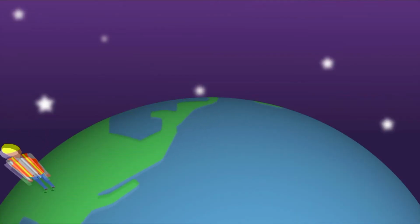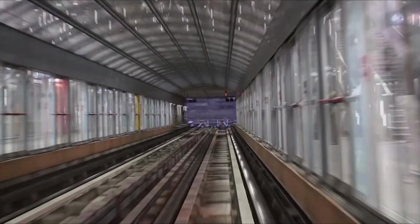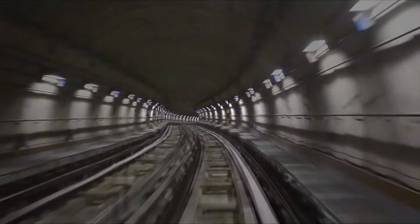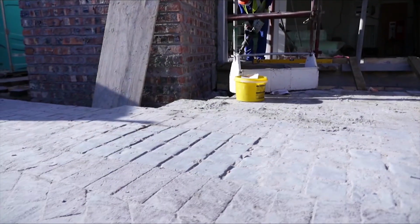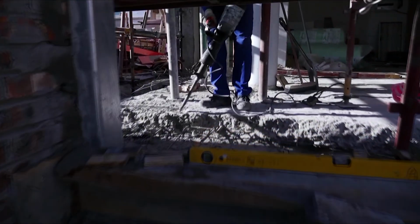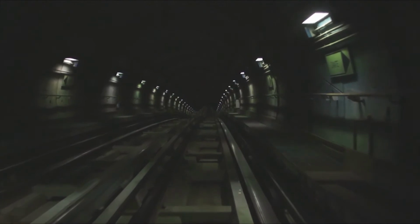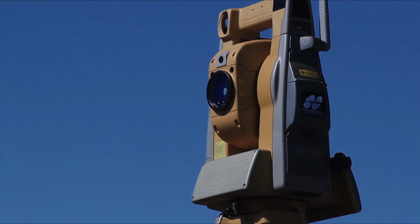The construction of this world-class system was a true international effort that included engineers, machinery, and technology from around the globe. Most of the rail track tunnels were excavated using drilling and blasting. This means that holes were drilled and filled with dynamite and detonated, causing rocks to collapse, lengthening the distance of the tunnel. Creating a circular-shaped tunnel requires careful calculation of the position and depth of each hole to be drilled and blasted. To calculate this, the Gautrain project relied on data from land surveying.